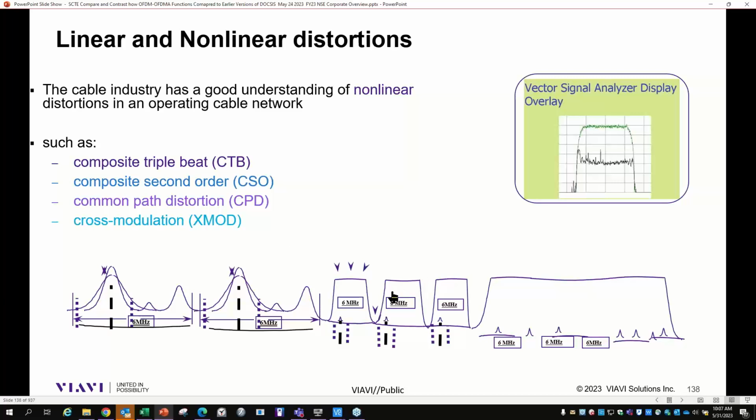In an all digital network, if this carrier goes up for whatever reason, the energy applies to this itself, but instead of seeing the video contents, as this particular carrier has multiple programs, what we see is a lower MER being introduced into the upper carrier. And that's why, if you look at your meter, it generally looks for adjacent channel greater than 3 dB, making sure that every carrier does not exceed a specific threshold in order to make sure it doesn't produce energy into the adjacent carrier itself. So these are anomalies that have happened.